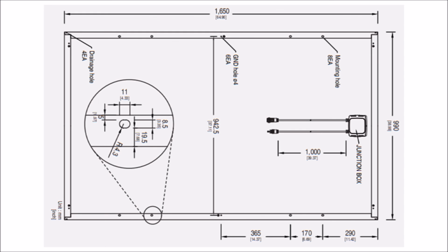Since we're starting with material selection, a more advanced material selection note is to review the voltage ratings on those MC4 connectors we were just talking about. MC4 connectors are standard in the industry, and some field-made connectors meet up with the plugs that come out the backside of the solar module. While these connectors are universal, not all are rated for 1,000-volt commercial systems, so that's good to check, particularly when you're installing a commercial solar array.